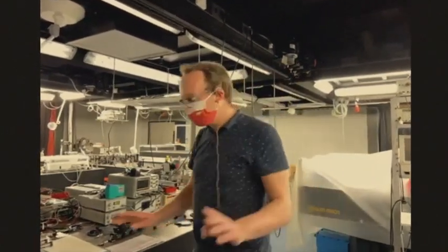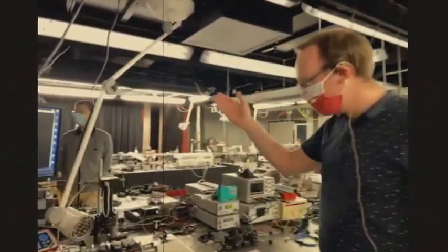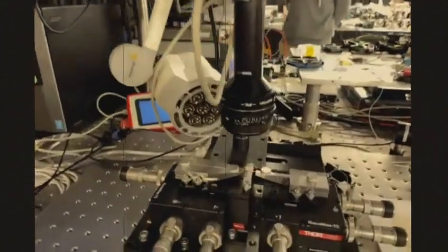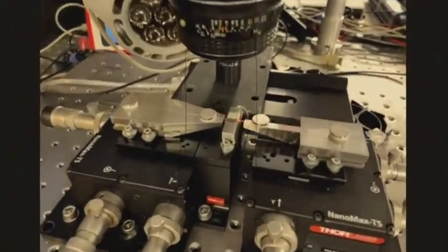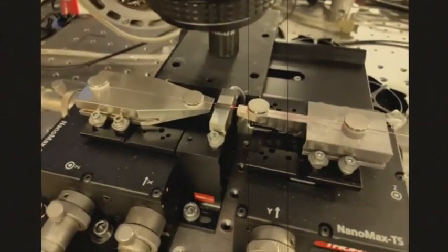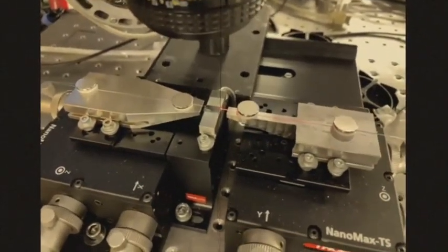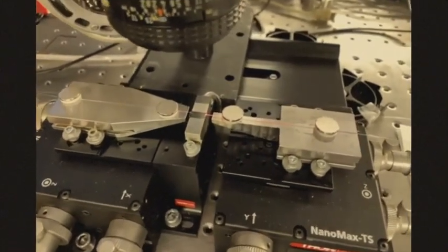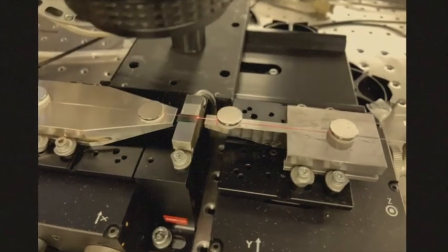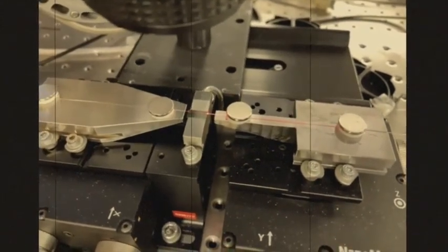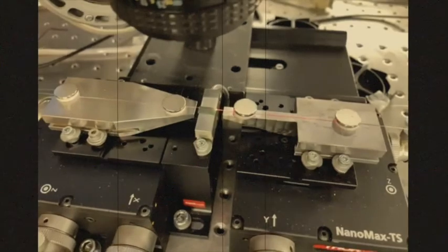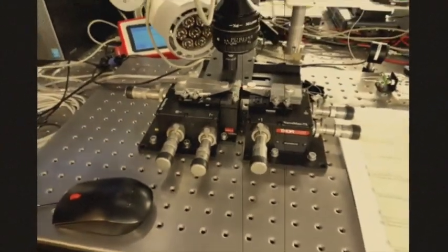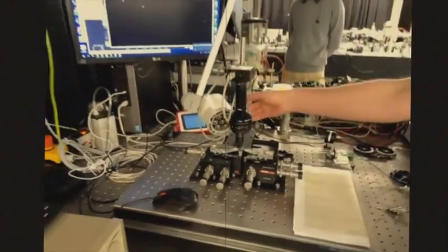Now, what happens here? This is kind of the heart of the setup. Here we have a small chip. This is also made of silicon nitride. It is produced in a different foundry, at Ligentech in Switzerland, because they excel at having different types of waveguides where the light is more confined in a smaller area for nonlinear interactions. At the moment, I am using a red laser for alignment, but most of the interaction happens in infrared.